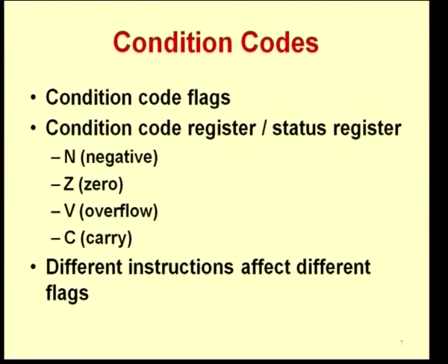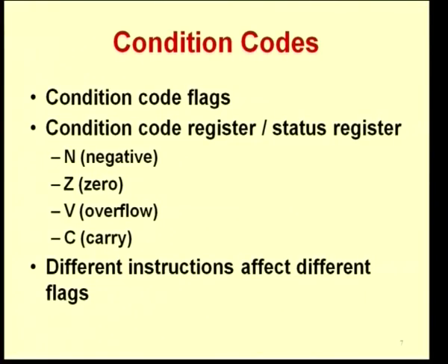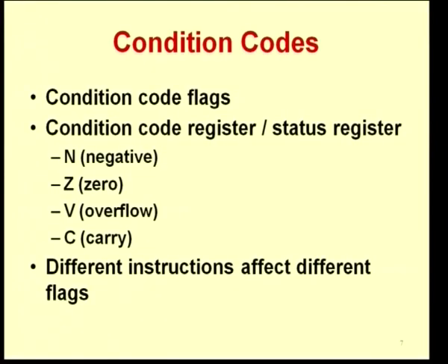You have overflow conditions when you are adding, let us say, two numbers and the result is not able to fit into the register. You have a value which is greater than what can fit into a register, you have an overflow condition. So, this is an overflow situation. The other is a carry. We all know what a carry is. So, in case a previous operation, say an addition, generated a carry, then the carry flag is set. So, these are typical flags that are set.